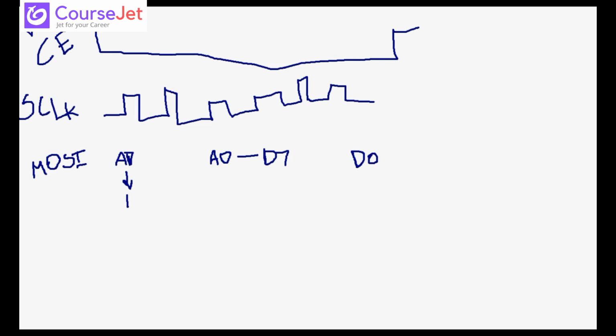But generally when we are displaying something, like LCD screens or LED screens at railway stations or for advertisements, you are not using only one byte. You will be seeing multiple characters at that time, right? That is called burst write. Burst write is a chunk or a group of characters. This is for a single byte, only one byte, so we will write here for multiple bytes. Suppose, say, 10 bytes. I'm just giving an example of 10 bytes.